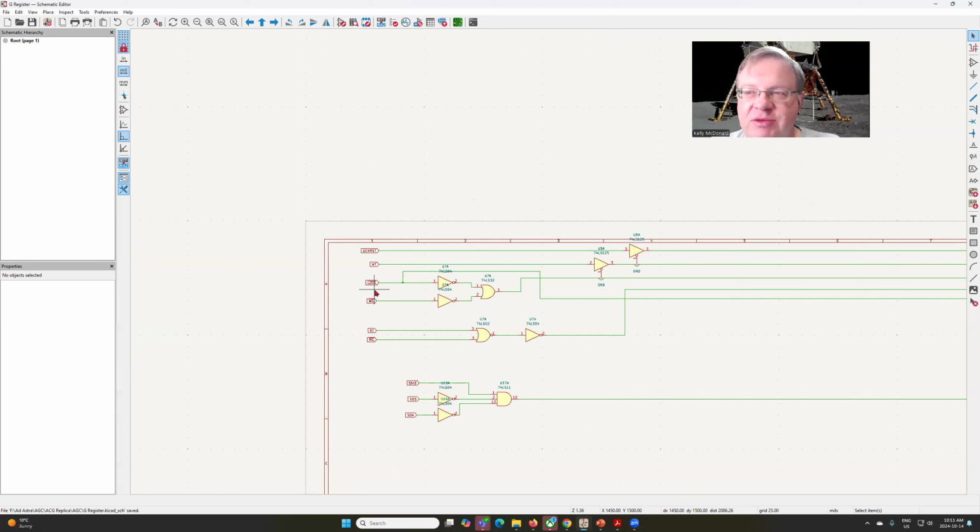If we're reading memory, we'll have to pull data from memory, and like I said, we'll talk about that in the next episode. And then we've got the read, where we push content out onto the write lines. That's just a simple RT NOR'd with RG. So it's our read timer combined with our read control pulse.